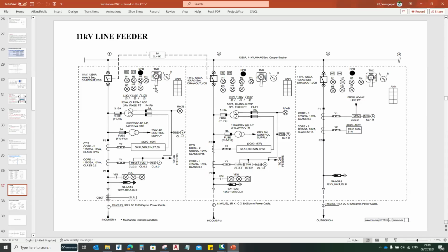And these are the indication lamps which will give the status of your circuit breaker closed, circuit breaker open, as well as the trip circuit supervision, as well as spring charge indication. Similarly, the TNC switch and local remote selector switch I provided. So the local or remote selector switch will indicate that you can operate from the local as well as from the remote. The remote can be either from the substation control system or from the remote control systems. And TNC will be used whenever you select the local operation. The TNC switch will operate to close as well as trip the circuit breaker.